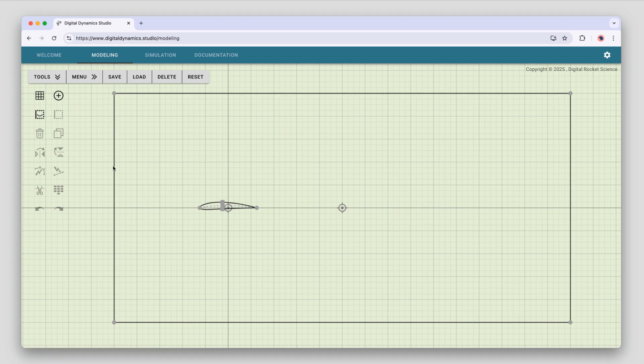The fluid will be coming in through this left boundary. You can check on boundary numbers to see what they are. Fluid will be coming in through the left boundary, number 2, and flowing over the airfoil, which as you can see here is boundary number 1, and leaving the domain through the right boundary here, which is boundary number 4. Then the top and bottom boundaries are number 3, and we're going to allow the fluid to slip along that boundary in the x direction but not penetrate that boundary. Basically, it constrains the flow within the computational domain, which is what we see here.